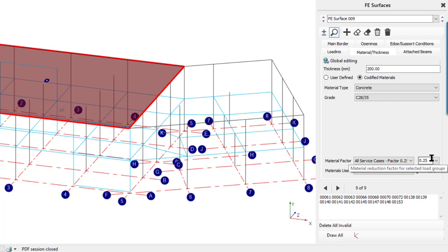That is as per, I think, the BRE Concrete Society guide on FE analysis of slabs using elastic methods. So we are modifying, in the service cases, all of our Young's modulus, so we get a more realistic indication of what the deflections under the slab will be. And then we just repeat the same on the next slab.